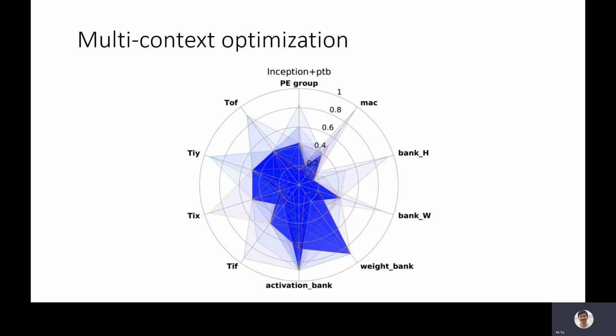We observed from the previous experiment that the optimized accelerator architectures diverge for different DNN applications. Hence, we then explore if there exist new optimization opportunities when very different DNN applications run simultaneously on the same hardware accelerator. First, we mix the Inception v3 and PTB by interleaving layers from both DNNs. Then we use the framework to optimize the accelerator architecture on this mixed DNN in a multi-thread manner. The operations from Inception and PTB run on the accelerator alternately.